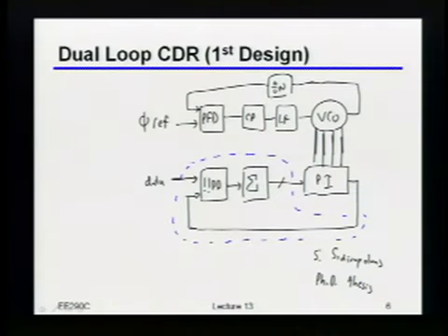Yeah, they're mostly digital, right? So that accumulator is certainly digital. Okay, the bang-bang phase detector, maybe we can argue a little bit about because that's your comparator or whatever. But basically, all of this stuff is digital, right? So that's nice because you don't have to worry about extra capacitors and extra loop filters and things like that. Basically, you can build a nice, perfect digital accumulator, okay?